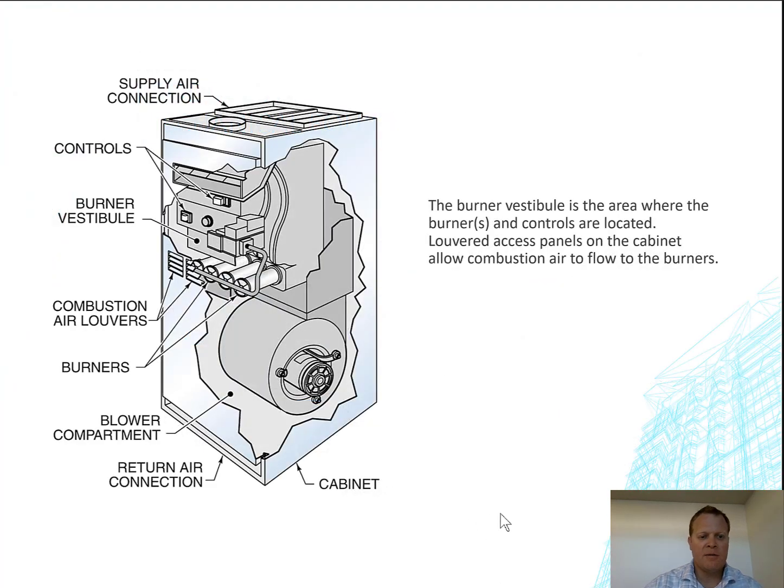Now, we talked about this already a while ago. So this is the furnace, and we've got a heat exchange going on here. This one's showing natural gas. We've got the burner here, and our clamshell right here. The blower's blowing air across this clamshell. The combusted gas is inside these little metal clamshell areas, and air passing over it absorbs all that heat and goes out to the house, right?